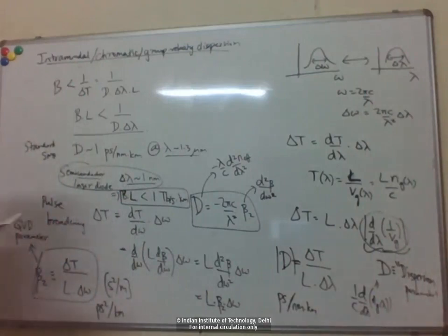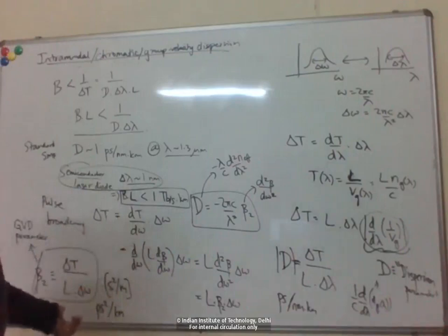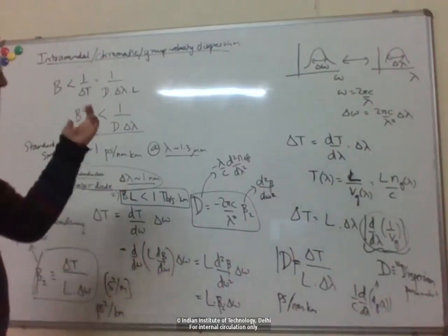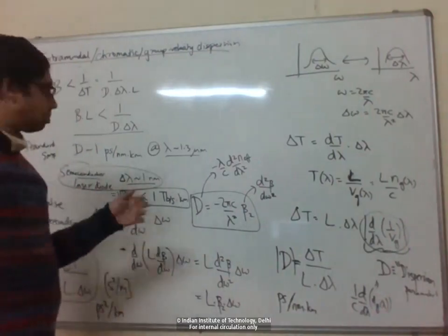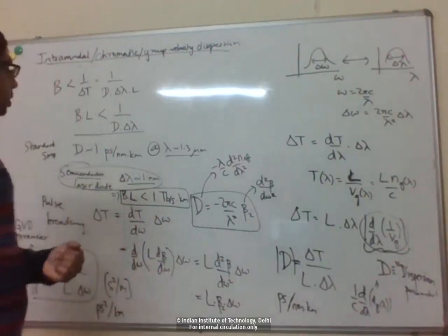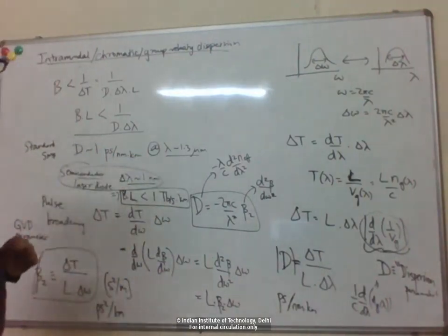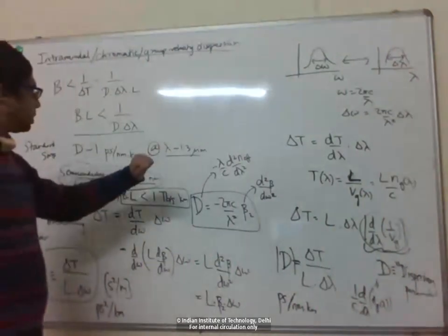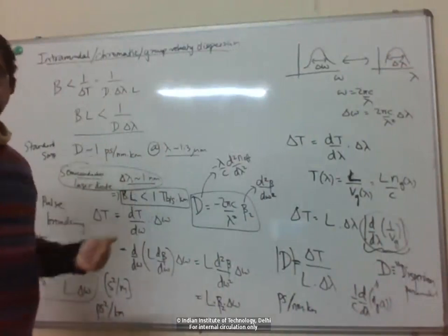Okay, so you can see how much we've improved going from multi-mode fibers to single mode fibers, right? In multi-mode, we were talking about megabit per second, gigabit per second, maybe tens of gigabit per second, but now here we moved to terabit per second. And these are with not even optimized numbers here, just operating close to the zero dispersion wavelength of glass with a reasonable laser diode.